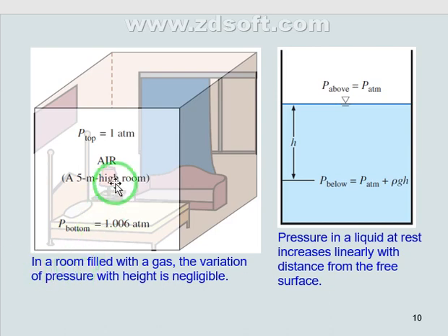If we apply the same concept for air, we still have the same concept, but when you say rho g h for air, it's very little and neglected, not like water, because the density of air is very small. It's about 1.5 kilograms per cubic meter, not like water, which is about 1000 kilograms per cubic meter.